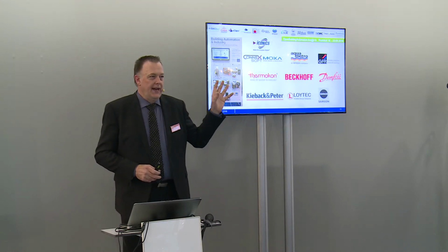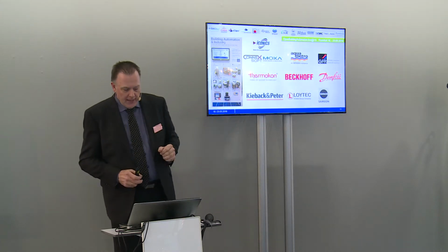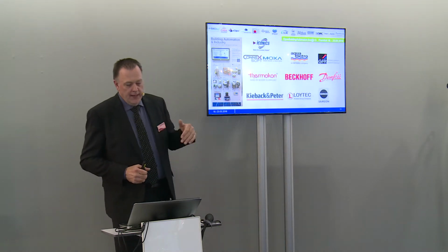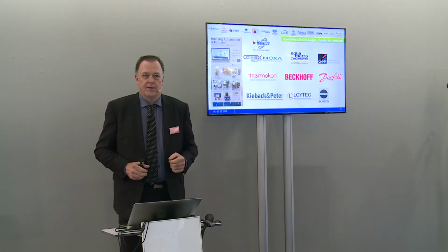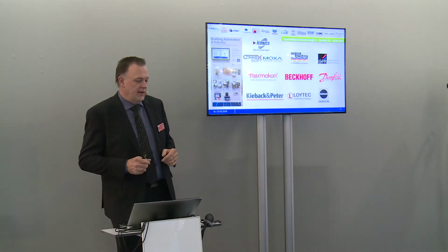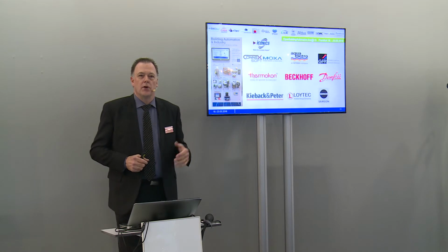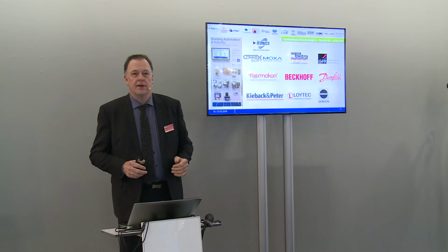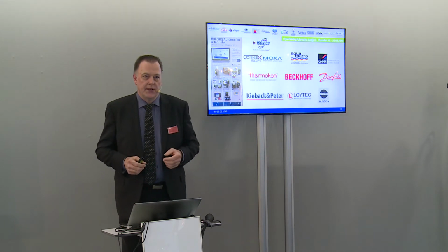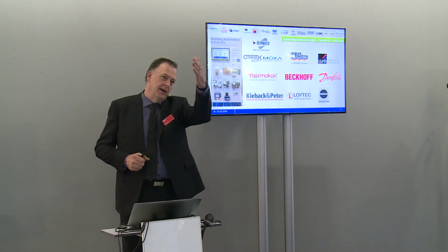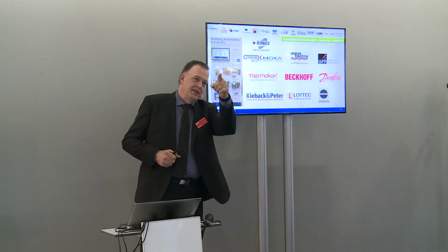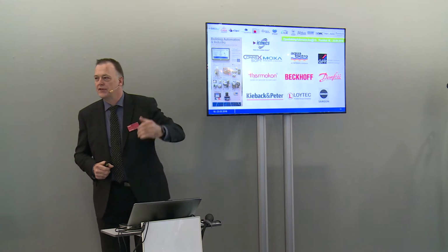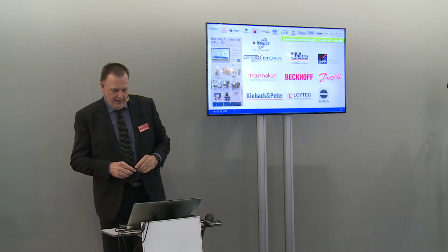So we have covered 8 BACnet devices using BACnet IP and BACnet MSTP. The gateway from Connexsoft is running on an industry PC, and this brings the data into OPC UA to Iconics at the very end, and brings it to the visualization system. We can see this demonstrator right this direction, so it's mounted at this wall, and if you want, I can introduce this to you in a few minutes after this presentation.